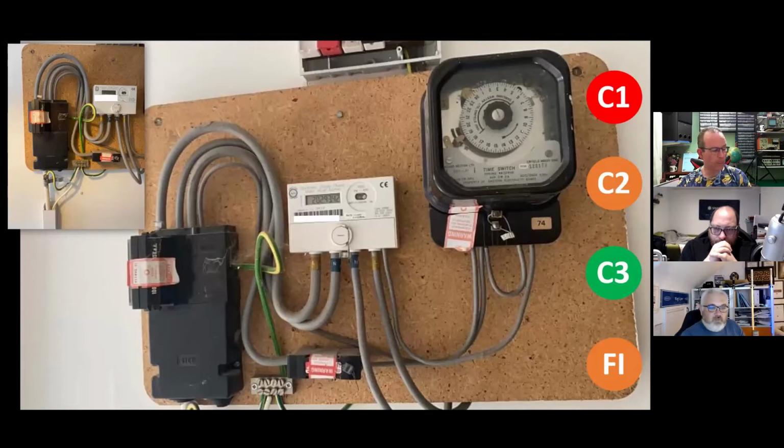And that's where it gets really complex. TN-C-S, TT, yeah. That's where it gets really complex. So for me, what you've got here is what was a TN-S, or someone has attempted to assume it's TN-S, but it's actually a TN-C-S with an end of line earth electrode. All of that is the DNO's. But you would think almost it's TT, TN-S and TN-C-S.